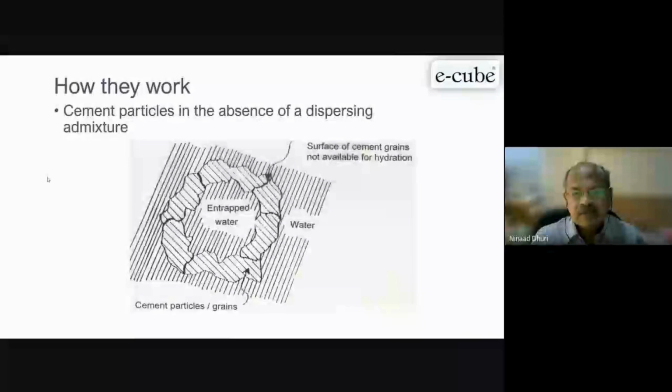In the sense that we need certain concrete for pile concrete, where high workable concrete. Then we have columns where we can use medium workable concrete, and then we have slab also. So if the grade is the same, but workability requirements are different, we need more flow or more slump, or we require any stiff concrete. So depending upon your requirement, we can choose the admixture to get more flow in the concrete or whatever workability you need. And all these admixtures basically